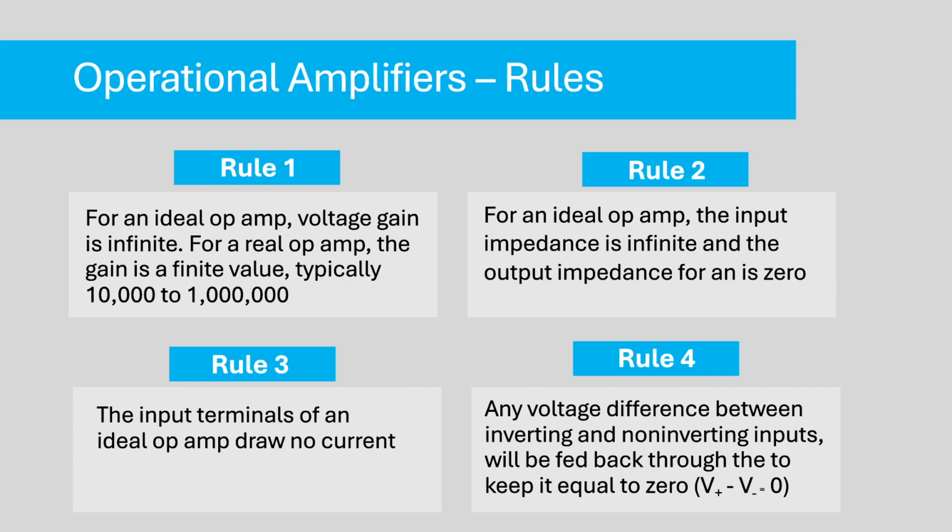As soon as it goes through, there is now feedback, and that goes back into the one input, and now it does it again with the input plus the feedback, and that goes through the amplifier and the feedback changes. That's a consistent cycle until it comes to a balancing point, and that's it trying to equalize itself and reach 0 essentially.